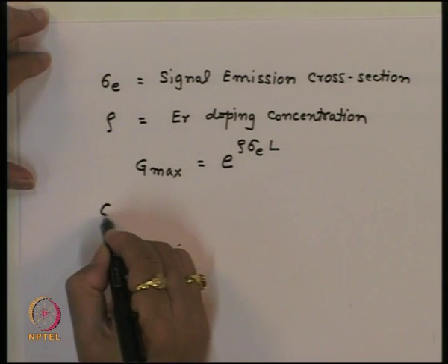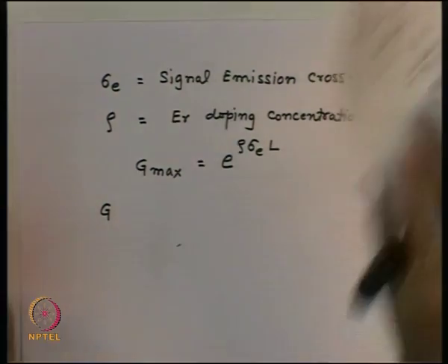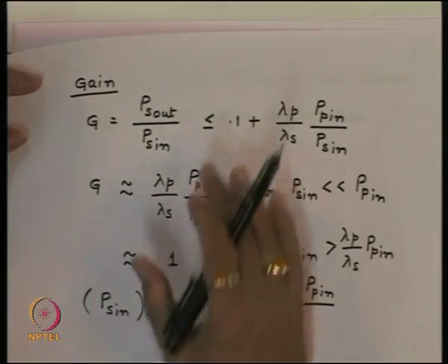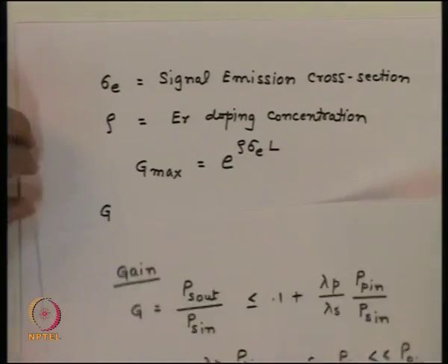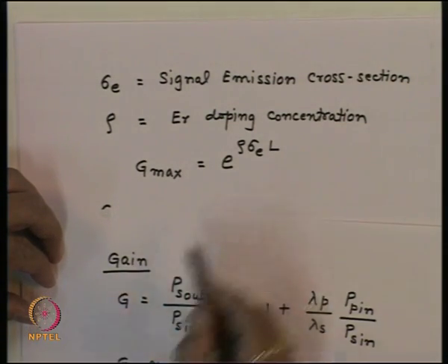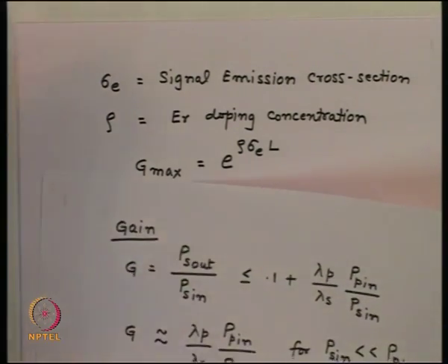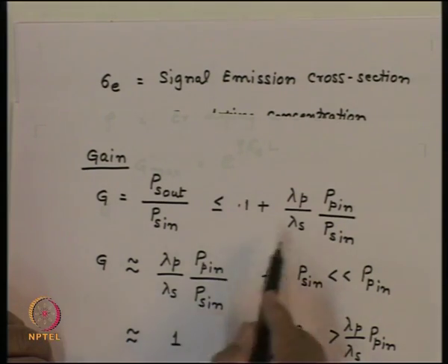Now, the gain actually depends upon two things. One is the saturation effect which we saw. As the power starts growing, essentially the gain will start dropping. So, I have the two things. One is this factor which shows the gain growing as the length is increasing, but as the signal starts growing, the saturation effect comes into the picture, and because of that the gain drops again.